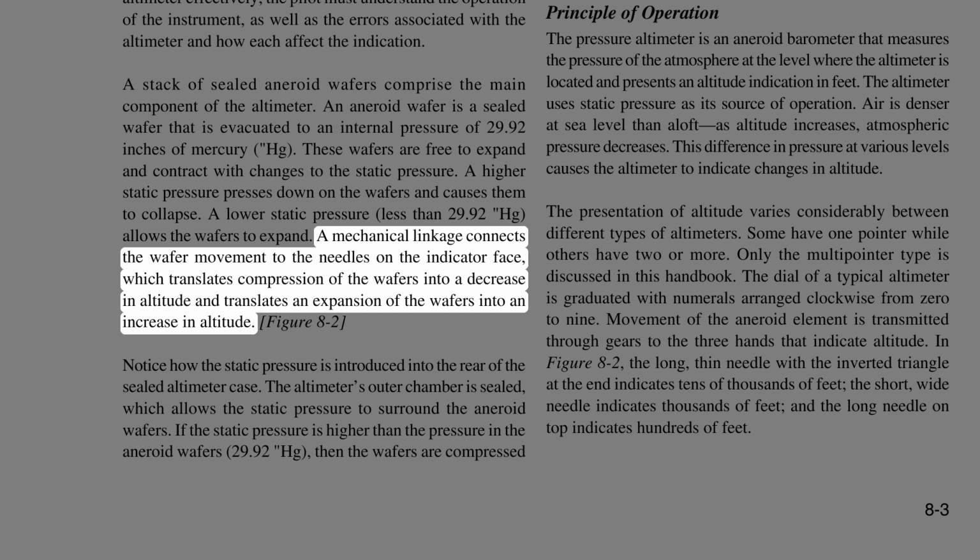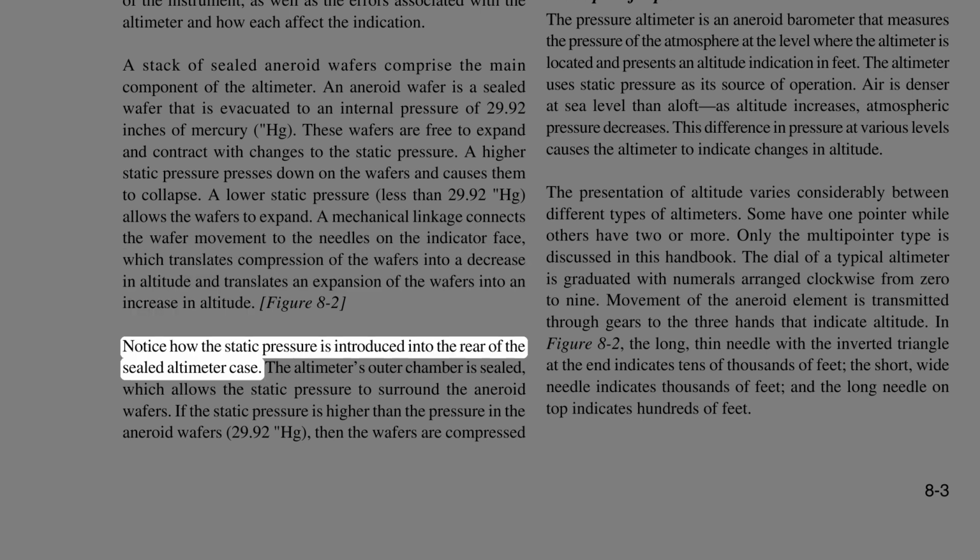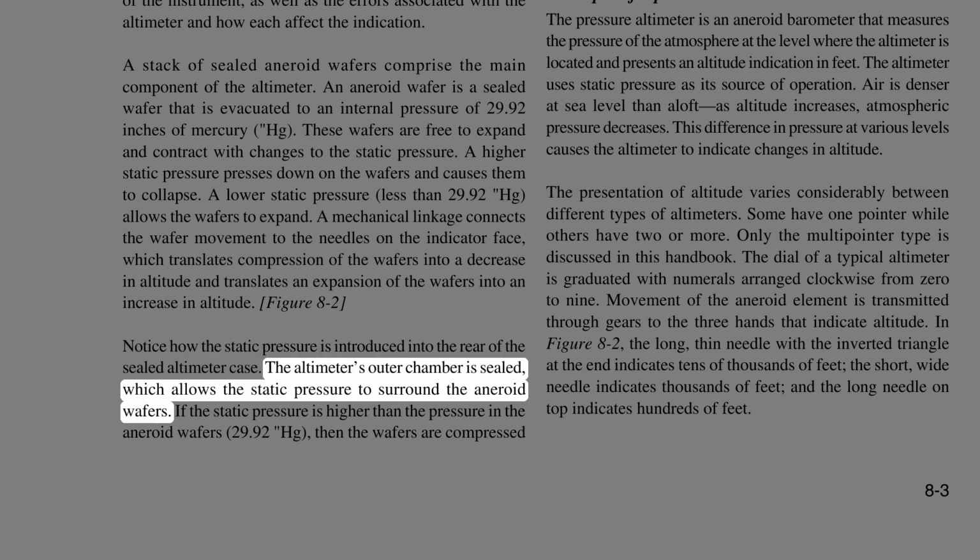A mechanical linkage connects the wafer movement to the needles on the indicator face, which translates compression of the wafers into a decrease in altitude and translates an expansion of the wafers into an increase in altitude. Notice how the static pressure is introduced into the rear of the sealed altimeter case. The altimeter's outer chamber is sealed, which allows the static pressure to surround the aneroid wafers.